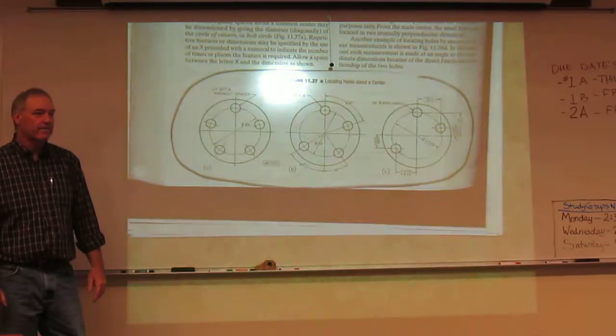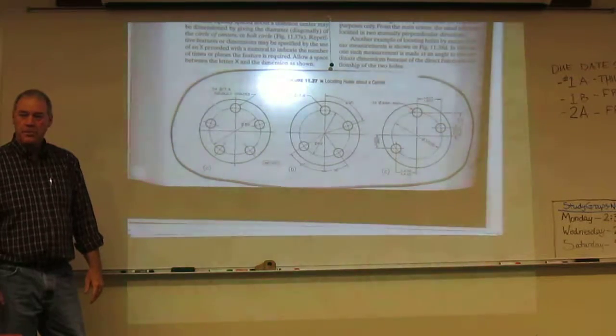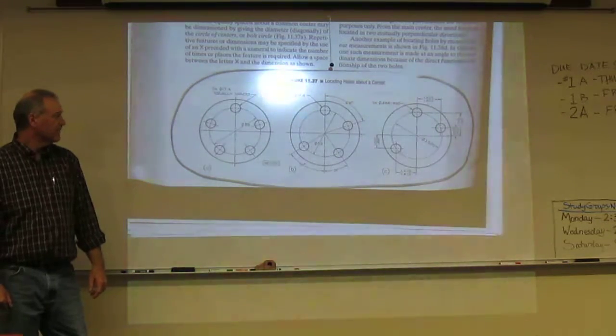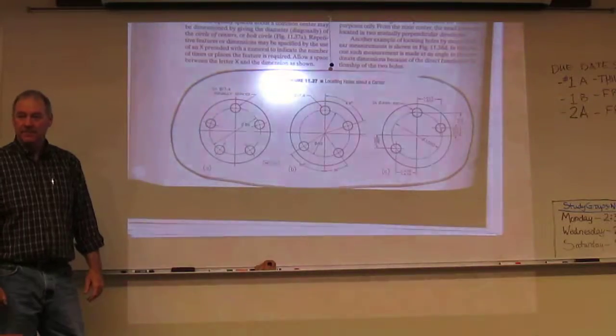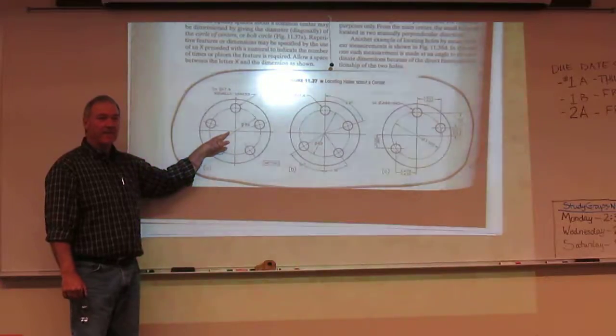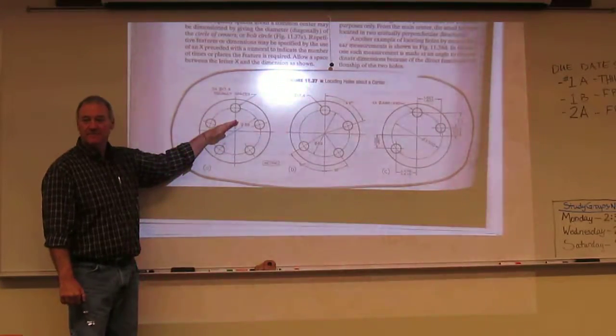Yes? Okay, another dimensioning: we did the radius from the inside and diameter coming from the outside. So now you've got the diameter coming on the inside of the circle. This is in the handout. This is still an ANSI approved deal for diameter, but we'll go over that later.